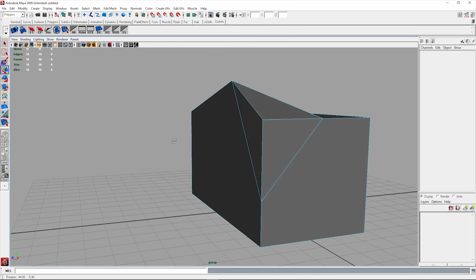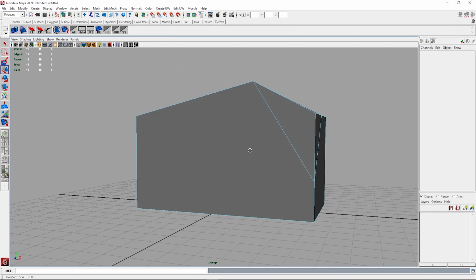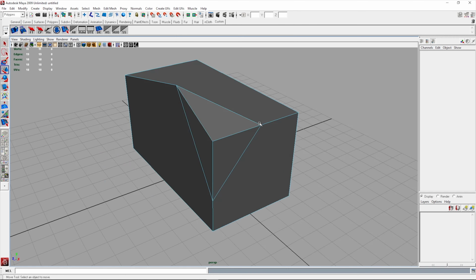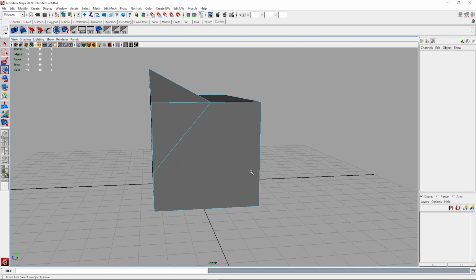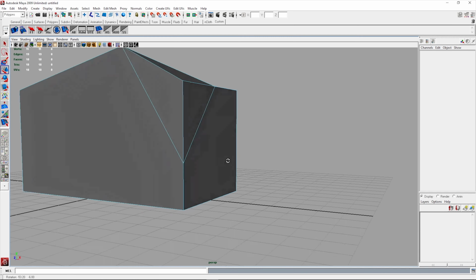But see, you've got the same issues on all of these sides now because when I cut these original marks, I didn't cut them along a vertex point, I cut them along an edge, and I've created a triangle and a 5-sided face. That's not good because of the way the software package convexes and concaves edges, and then you don't have full control, and you can come into a lot of issues later.